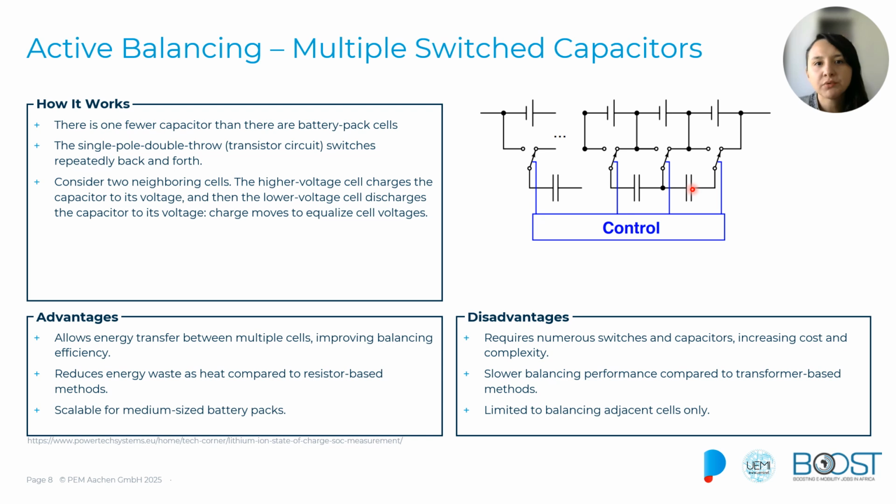This cycle will be repeated across the entire battery pack until all of the battery cells are balanced. In general, unlike passive methods, this technique is way more efficient, and it reduces the thermal stress of the components and of our batteries, also improving the reliability of these systems.